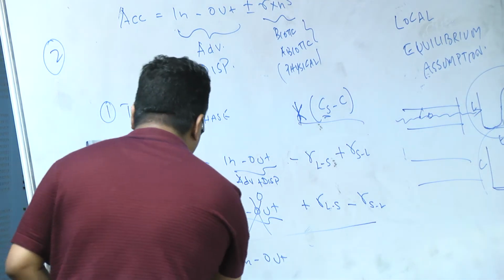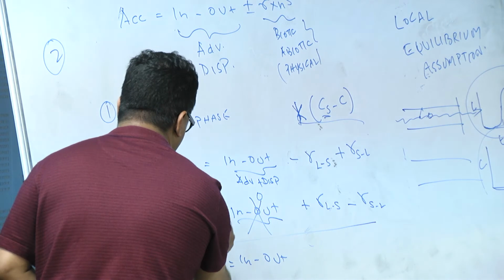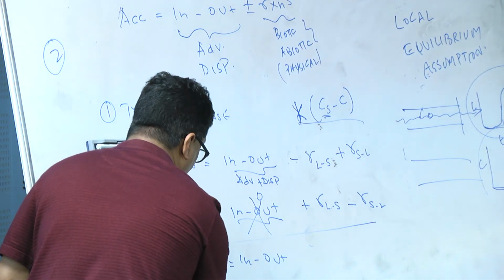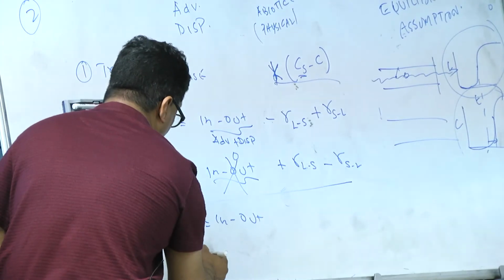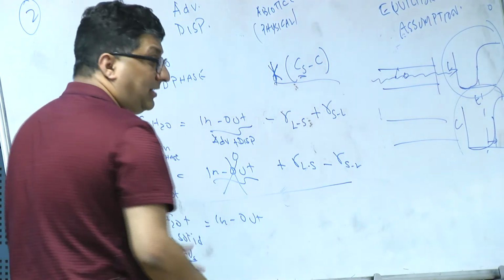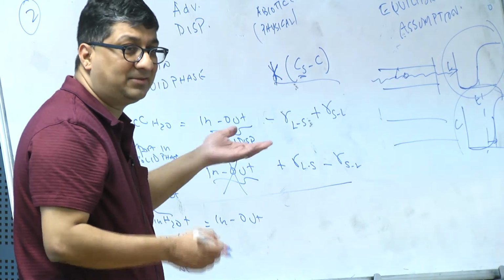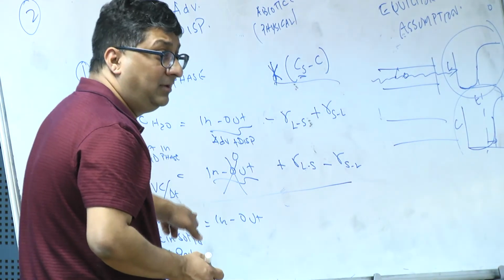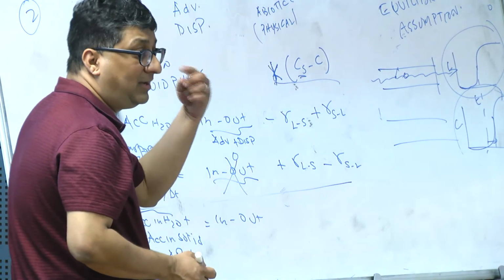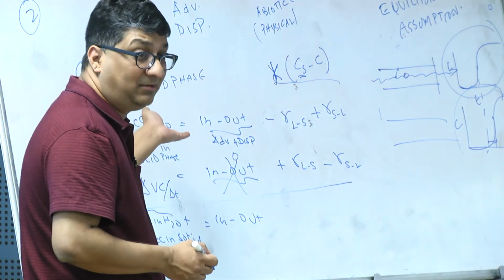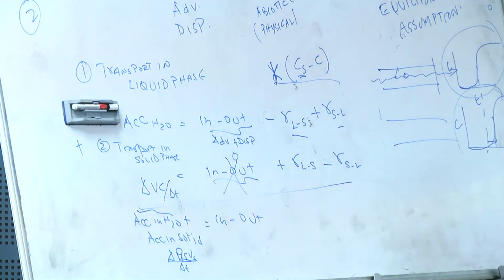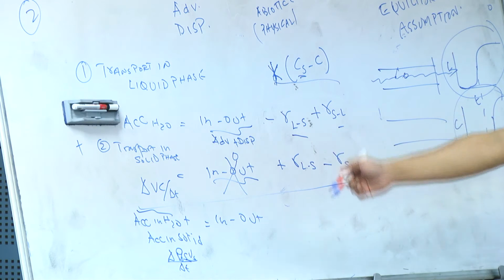Okay. This will be written in terms of del T. This will be written in terms of density, because the solid phase concentrations are written in milligrams per kilogram. So, I just have to convert it using bulk density. So, I have two unknowns, C and S, one equation. So, I need one other equation to solve this, because I have two unknowns, I need two equations. If it was kinetically controlled, this kinetics and this kinetics will not be the same, and I would have one equation for the kinetics and one equation for mass balance, because there is a net movement in one direction.